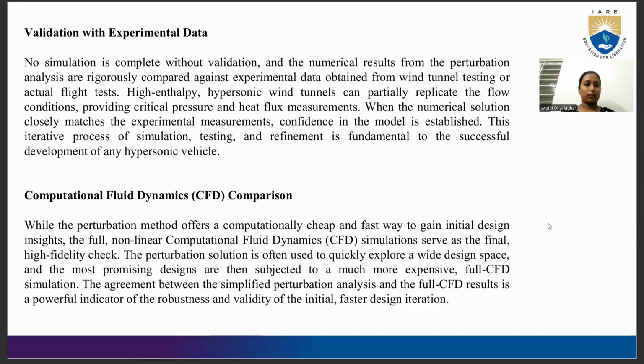Validation with experimental data. No simulation is complete without validation, and the numerical results from the perturbation analysis are routinely compared against experimental data obtained from wind tunnel tests or actual flight tests. High enthalpy hypersonic wind tunnels can partially replicate the conditions, providing critical pressure and heat flux measurements. When the numerical solution closely matches the experimental measurements, confidence in the model is established. This iterative process of simulation, testing and refinement is fundamental to the successful development of a hypersonic vehicle.